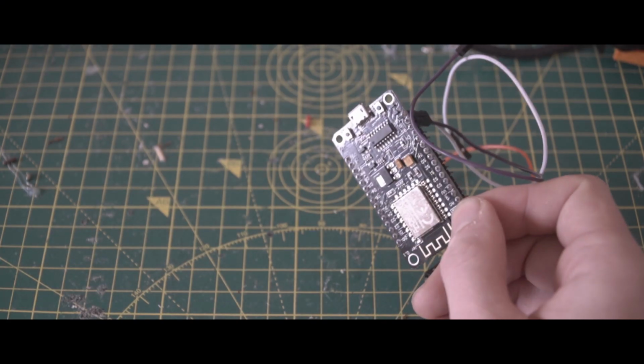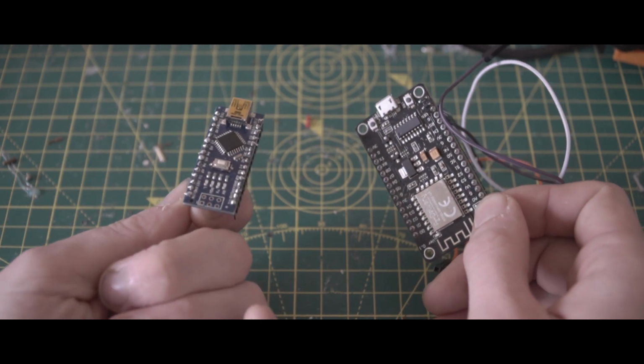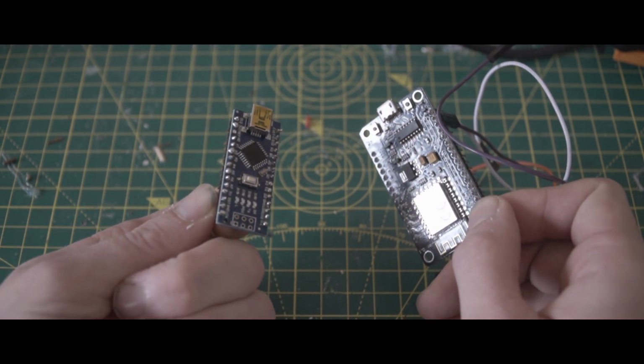Oh, and just to make things a little bit more complicated, I'm using a Node MCU, which is a different kind of microcontroller, similar to an Arduino, but with a Wi-Fi chip built in, to send average distance data as an 8-bit integer with UDP over Wi-Fi to Max to eventually modulate something. Oh, and Max is talking back as well, so it's sending number values to the light to tell it which pre-programmed animation to play. So everything's talking to everything and it's all connected.